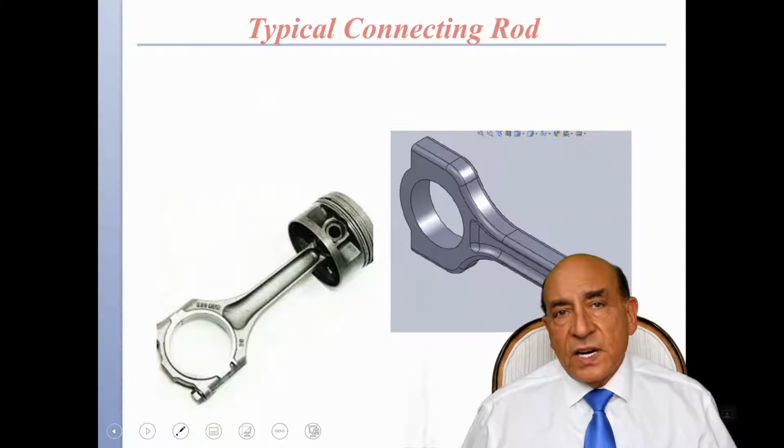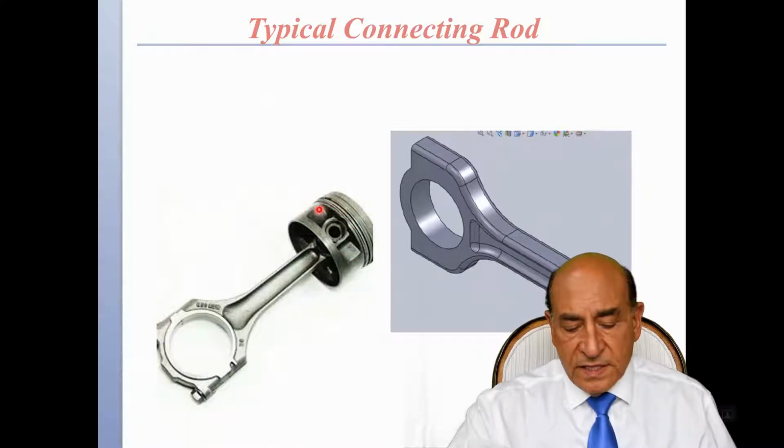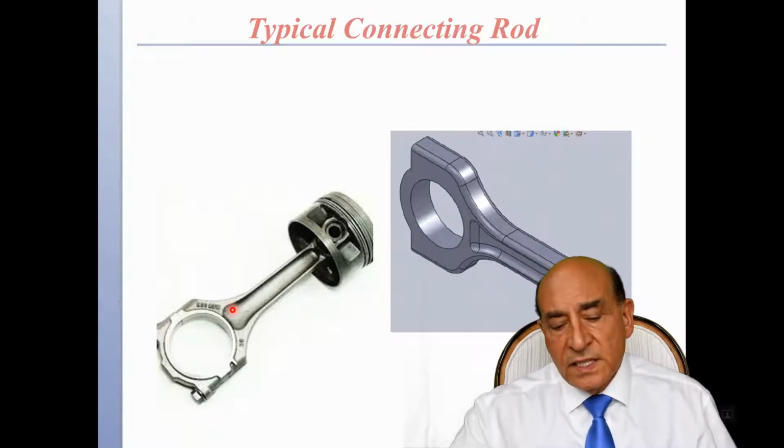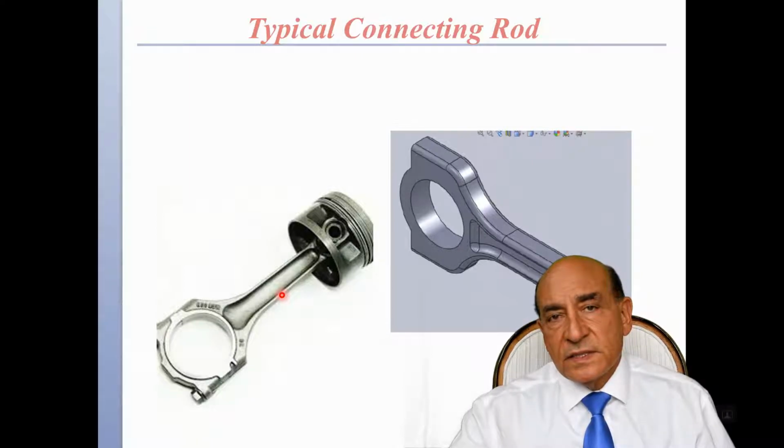The connecting rod looks like this in general. We have a cylinder connected to the rod, and you can see it kind of carved out in the middle area here. And the reason it's carved out is that you try to minimize the weight. So it's similar to the idea of the I-beam.